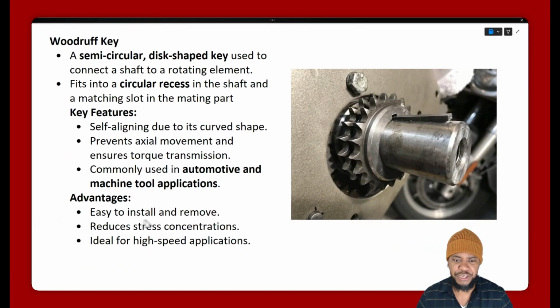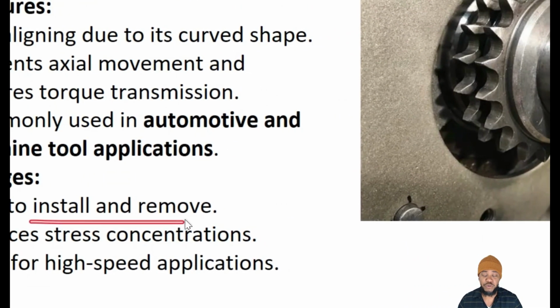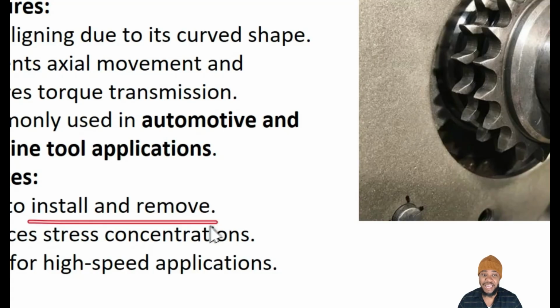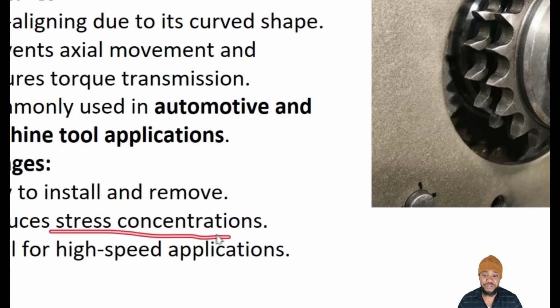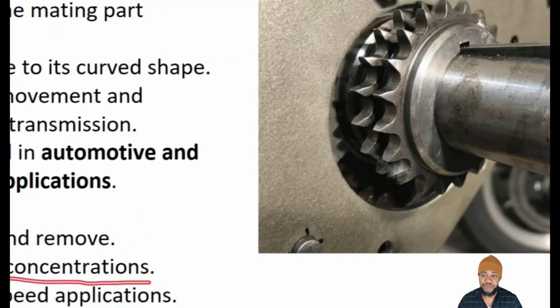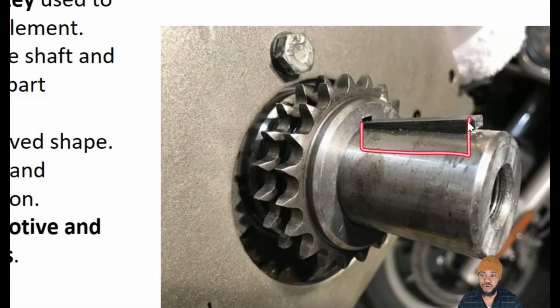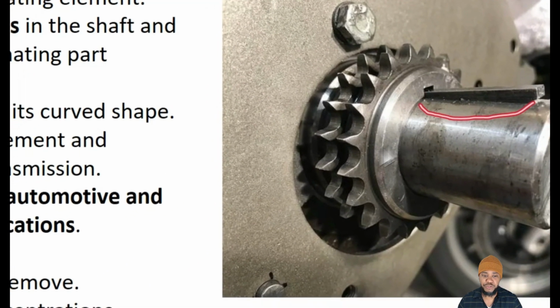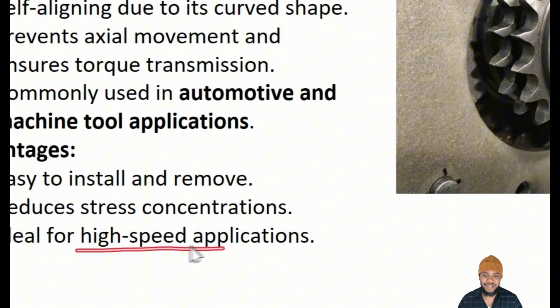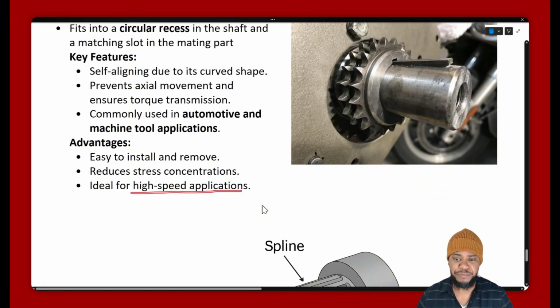Some of the gifts of Woodruff keys. They're easy to install and remove. They act to reduce the stress concentration because rather than having sharp corners, they have a continuous curved surface. And so they're ideal for high-speed applications.